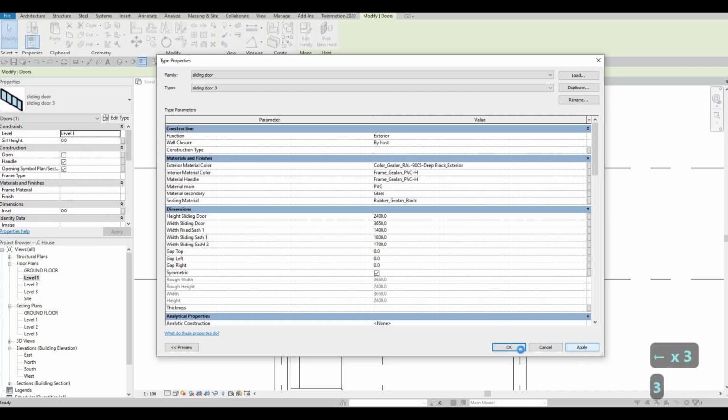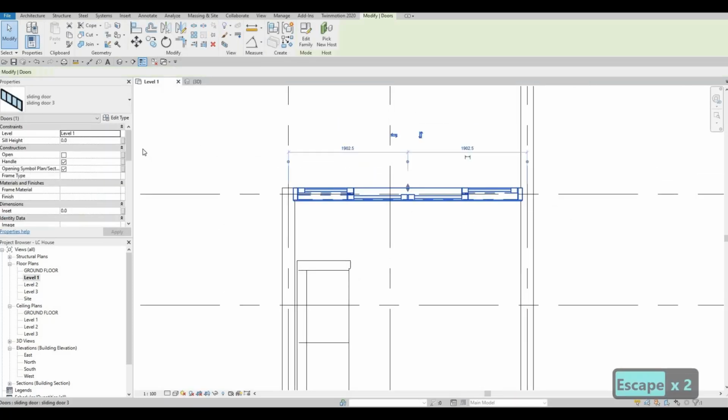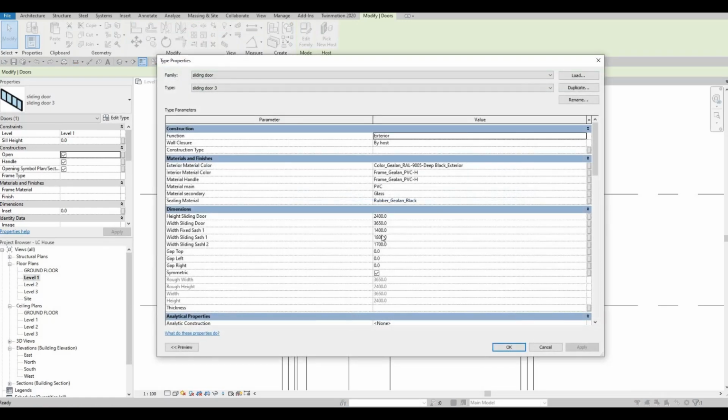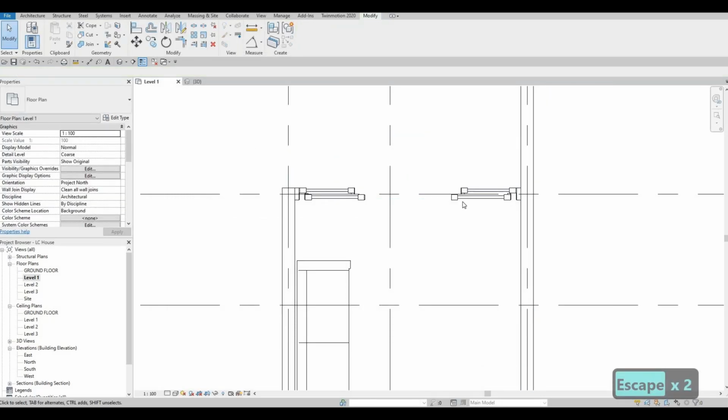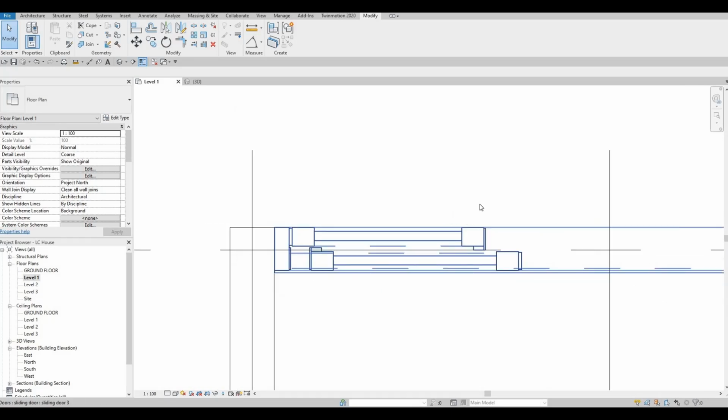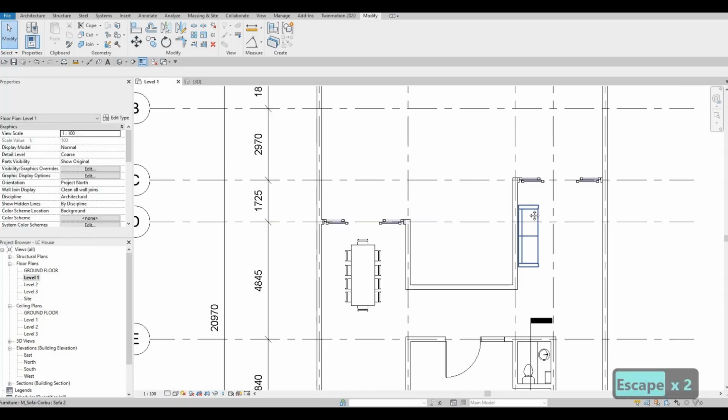3650, just to give that room there. And the good thing about these parametric doors is they're very nice to use, because you can open and close them instantly. You can edit the blocks with height, and here let's make it 3600, because I don't like the mullions or the trims inside the wall, and it doesn't look good. So at least now at 3600, it's mostly outside, and it looks really fit from there. So at least we have it there.